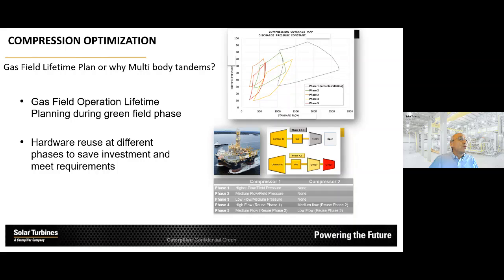Now, the neat thing about the modular rotor is that in these restaging procedures, you don't necessarily have to exchange entire rotors. You may be able to get away with just replacing one or two impellers, or also reusing these impellers at later stages of the project. So that gives you a lot of extra flexibility.